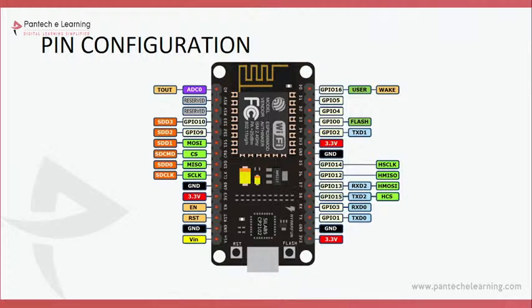And this RX and TX is there now. This is for receiving and transmitting data from different wireless networks like Zigbee, LoRaWAN. For all these wireless network purposes we use RX and TX for communication between the two devices. Like, we have three protocols: the UART protocol, SPI protocol, I2C protocol. These three protocols are used for communication.